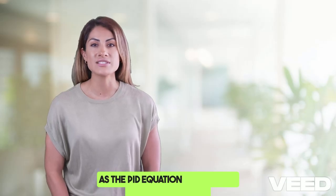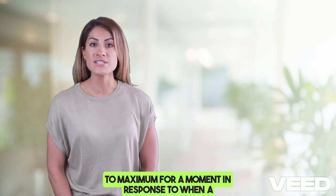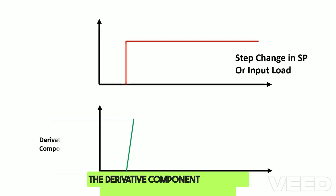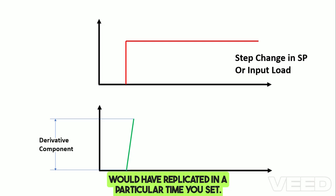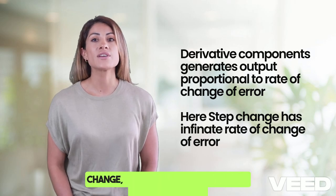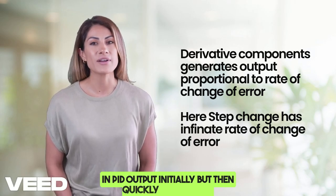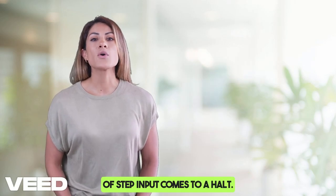As the PID equation says, the PID output will shoot to maximum for a moment in response to when a step change is applied due to derivative control action. The derivative component says I will generate an output whenever I see there is a rate of change of error, and it will be as strong as the proportional component would have replicated in a particular time you set, I mean derivative time. Since a step change has an infinite rate of change, the derivative term creates a sharp spike in PID output initially, but then quickly settles and stops generating any output as the rate of change of step input comes to a halt now.